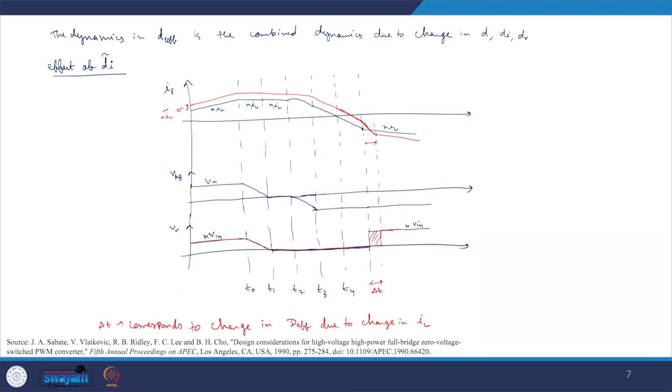If you look very carefully, this particular slope is coming across the L leakage, and if we recall our expressions for that, because here it is T4 and here it is T5, during T45, if you recall, our T45 is nothing but L leakage, we have NIL at T5, and that is nothing but L leakage times NIL at T5 divided by V in.